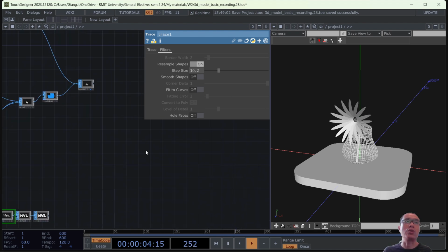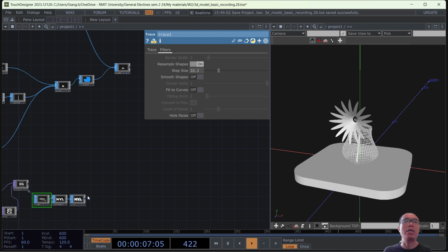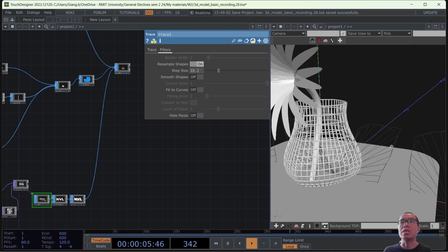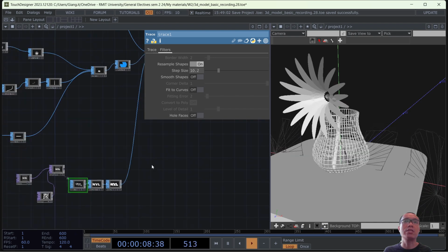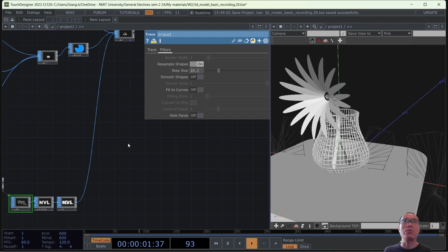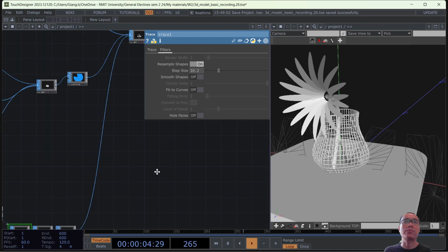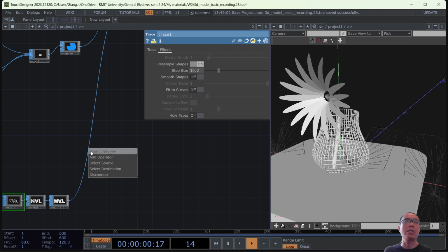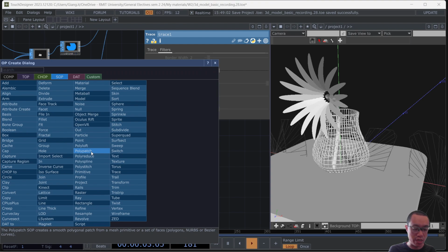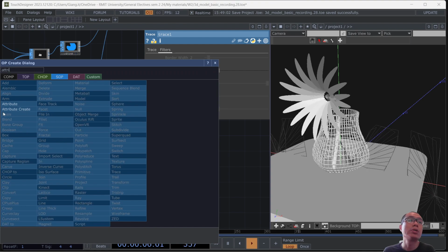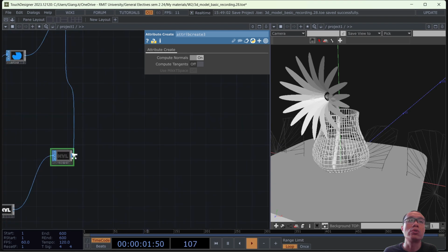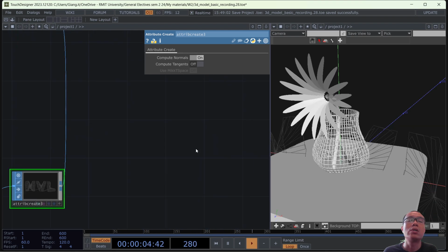merge this one to the geometries by drag and drop this into the geometries, and you see this showing over here, but basically the normals over here is inverse. All right, so we need to click on the insert operators over here and add in an attribute create, and click on compute normal. Okay, so that we have the normal here is going on, but it's still